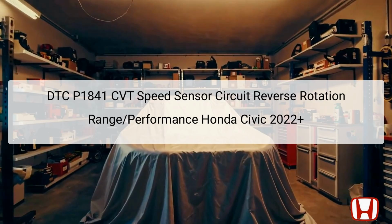Addressing P1841 is crucial for maintaining vehicle performance and ensuring smooth operation of the CVT, a transmission type that allows for seamless acceleration. It's important to note that the CVT contains no fixed gears. Rather, it uses pulleys to provide the necessary gear ratios, adapting to driving conditions seamlessly. In this presentation, we will delve deeper into the symptoms, causes, and detailed troubleshooting steps to appropriately resolve this issue with the CVT speed sensor.